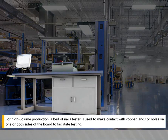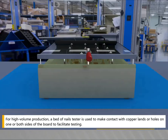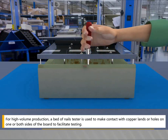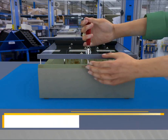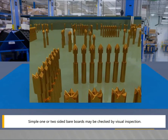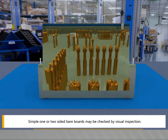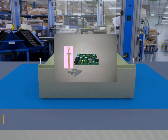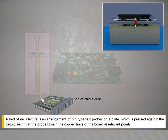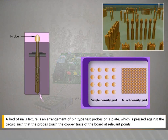For high volume production, a bed of nails tester is used to make contact with copper lands or holes on one or both sides of the board to facilitate testing. A bed of nails test fixture is unique for every PCB layout. Connections to the board under test are made by a comprehensive bed of nails fixture. A bed of nails fixture is an arrangement of pin-type test probes on a plate, which is pressed against the circuit such that the probes touch the copper trace of the board at relevant points.